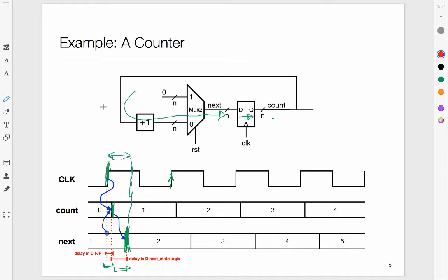At the same time, our gates have become very fast. And as we shrink the devices, as we shrink our chips, wires get thinner. As wires get thinner, what do you think happens to their resistance? It goes up, right? Thinner wire, so less conductance, and therefore the RC delay goes up. So essentially wire delay dominates.